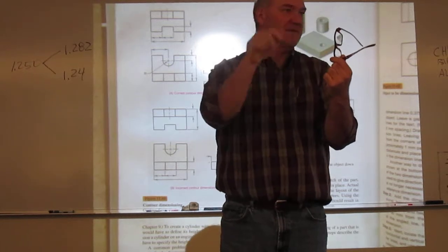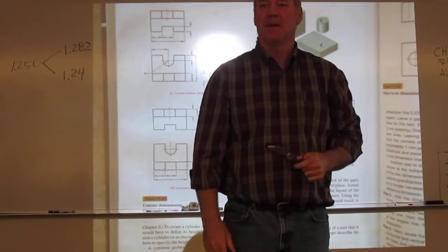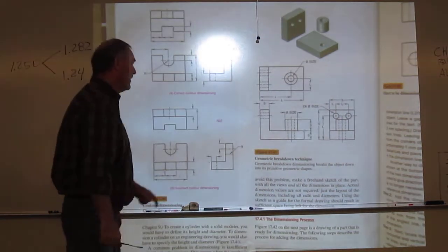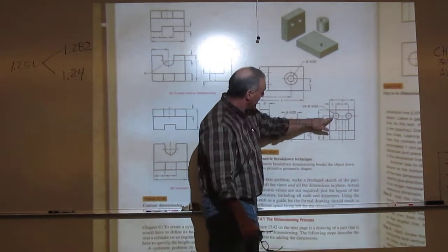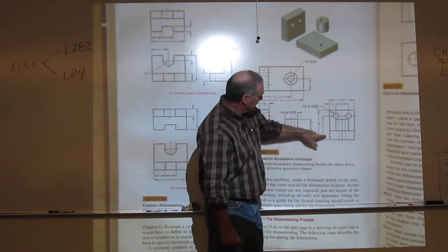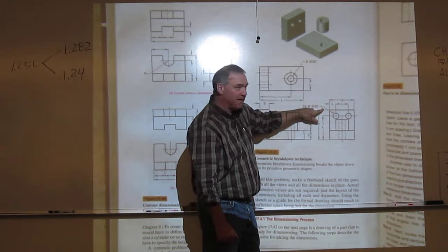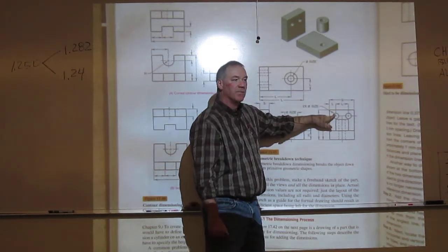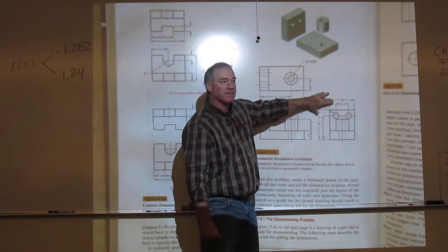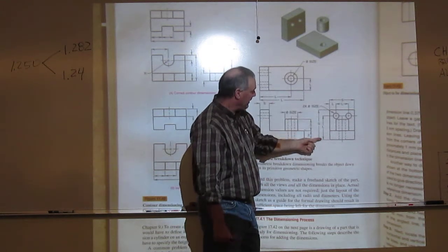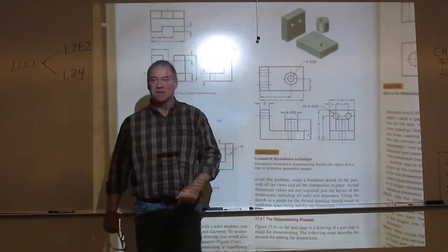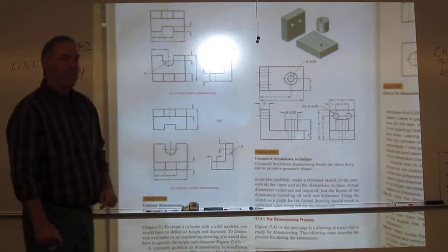Saying, okay, I need that, I can build it. And they're not hunting for these. Okay, grouping. This one over here really has probably the better example on these two negative cylinders. Here they've located it across the top, they've located it on the left side, and they've sized it right here with it. Good job of grouping on that. There's association, they put it in between. It's also contouring. We see the best look at it right here.